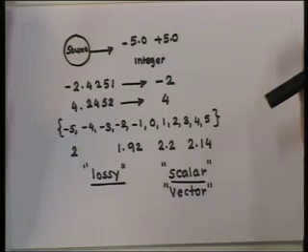Though the process of quantization is very simple, the design of the quantizer will have a significant impact on the amount of compression that can be obtained and the loss incurred in a lossy compression scheme. Let us examine the issues related to the design of quantizers in a little more depth.